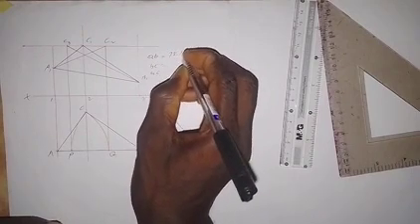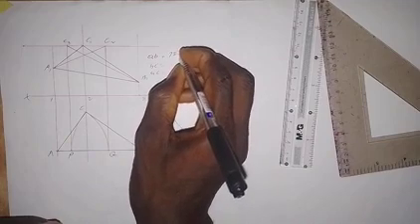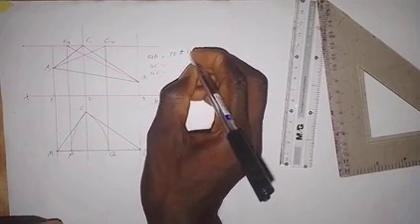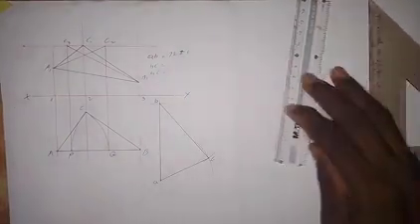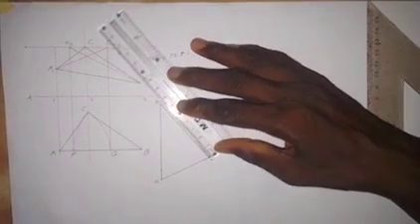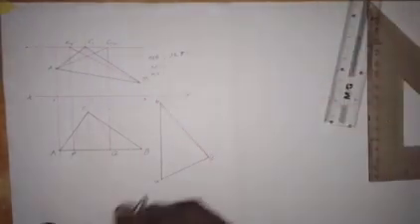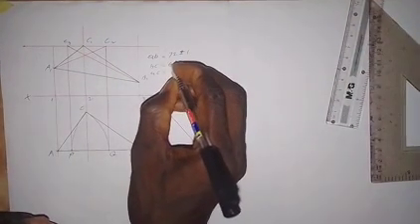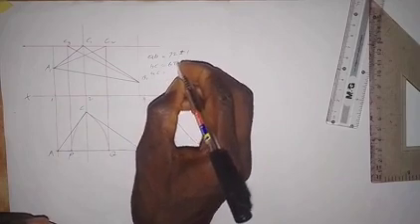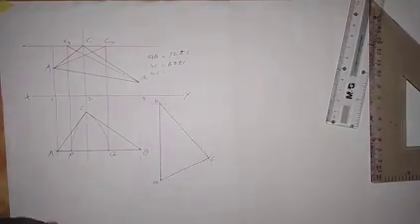You have to write plus or minus. This is how we state it in technical drawing. So plus or minus 1. Then what about BC? If I take this measurement from here, BC is 68, so 68 plus or minus 1.